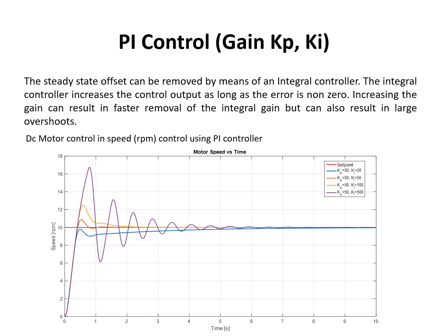So now we're looking at the PI controller on the speed controller. Now the idea here is that we basically add a pole at the origin, and this converts the system to a type 1 system, where we will now have an error of 0 if we have a PI controller effectively.